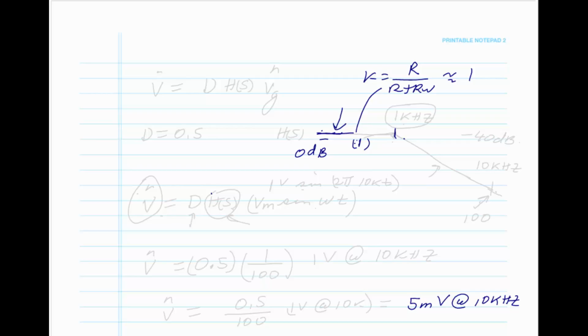And that could be from other inputs that get the AC waveform, which is 120 hertz after a full bridge. It gets all kinds of signals onto the input from other converters turning on and off in the input stage. So that represents low and high frequency. It has nothing to do with switching frequency. Okay? So we have our transfer function.